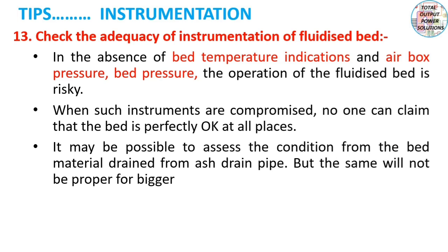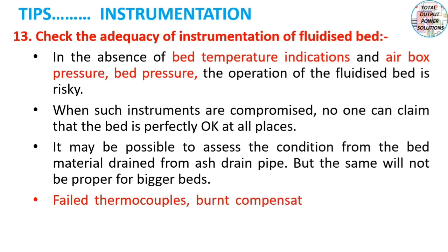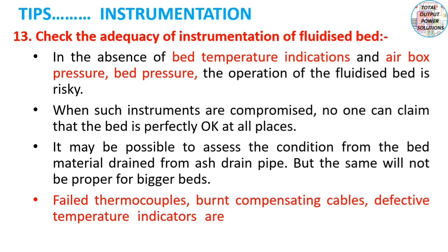Failed thermocouples, burnt compensating cables, and defective temperature indicators are to be replaced at the earliest opportunity to prevent bed coil erosion.